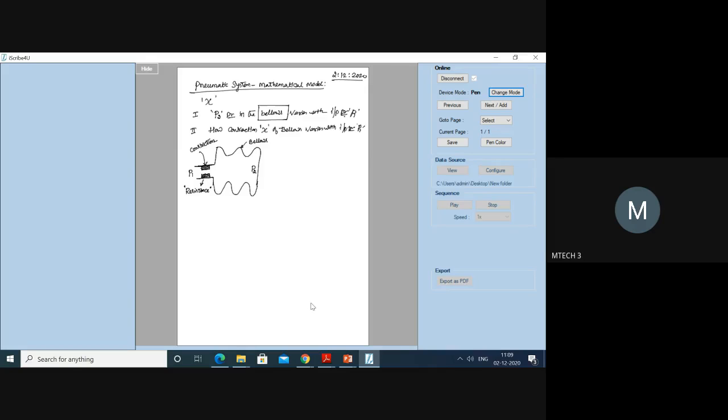The other one is the bellows. The bellows is going to give you the capacitance. Capacitance is nothing but the air carrier or the storage. Now write those two, resistance and capacitance. Then the rate of mass entering here is m dot. m dot is nothing but dm by dt, the rate of change of mass with respect to time.